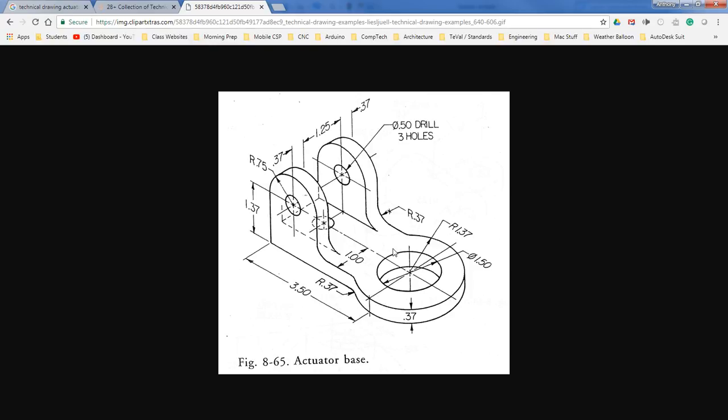I'm thinking about how we would like to model this, as I know from the back of this rectangle that I just drew to the front is 3.5 inches, which marks the center of the circle. At that point, I'm going to take the center of the length side of the rectangle, at the end at 3.5, which will mark this, and then we're going to drag out a 1.5 inch diameter circle, followed by another 1.37 inch radial circle.